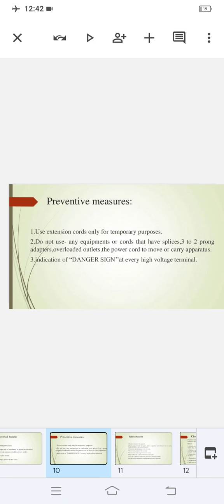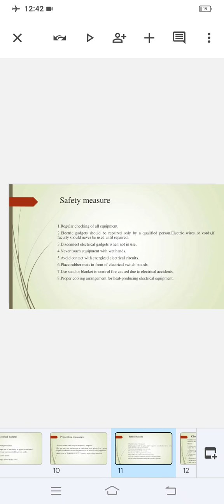Capacitors can store current after the power supply has been shut off. Capacitors also should be discharged, and hence the power plug has to be disconnected from the mains after working. It should be properly checked, and fully trained and authorized personnel must engage in the inspection, repair and replacement during the maintenance work. If necessary, protective clothing and safeguards should be used by all those authorized personnel.